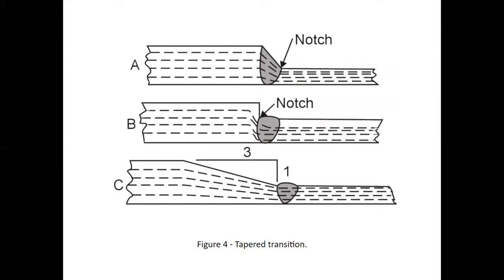That's why, if you weld with a big convex cap, the stress flow lines are going to flow across the face of the surface, hit the edge of the cap, turn, move through the cap, come down, turn, and then move back to the plate. It's similar to what we see in this middle graph with the notch effect, where everything makes a hard turn down. This would be likely to fail, and it would start cracking right here, probably just on the outside of that weld, and it would fail there.